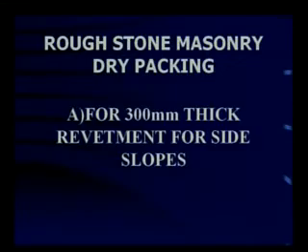Why do we need a revetment? We need a revetment as a protecting layer, a blanket of stones, so that the slopes do not slide away. To protect them we need a revetment. In this particular problem, I have taken the thickness of the revetment as 300 mm, right?